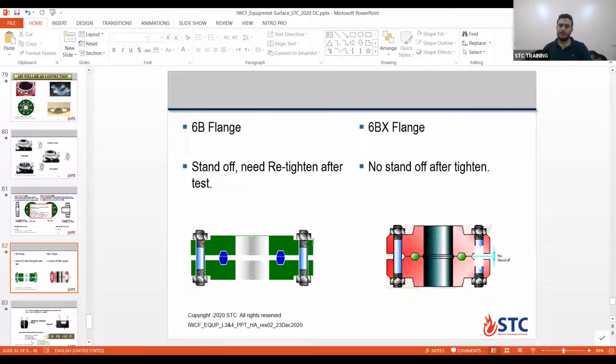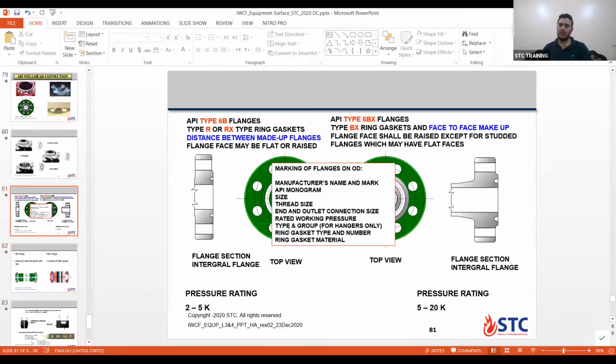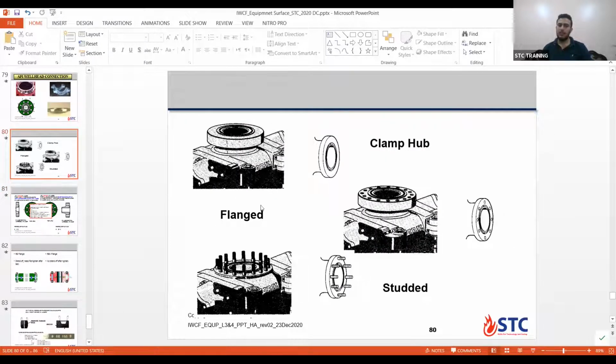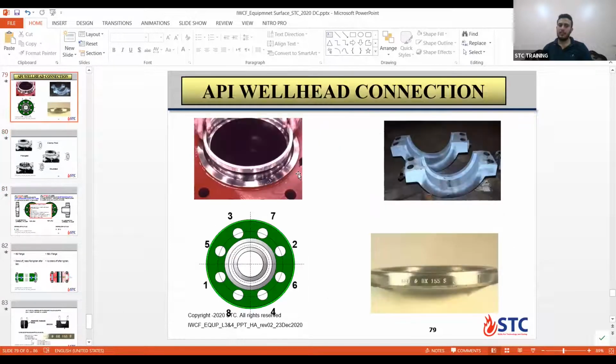Coming here, for installing the ring gaskets, this groove needs to be clean and dry. Then we use the ring gasket in its place to add more seal. Ring gaskets are only used one time. Even if its visual inspection is good, it is used only one time.